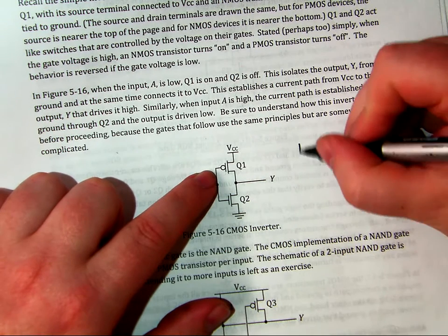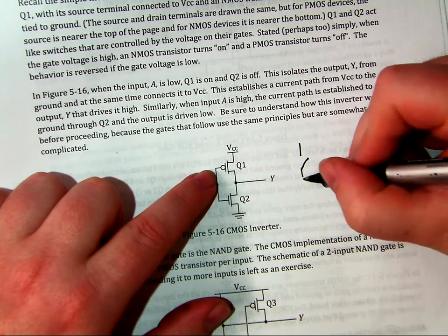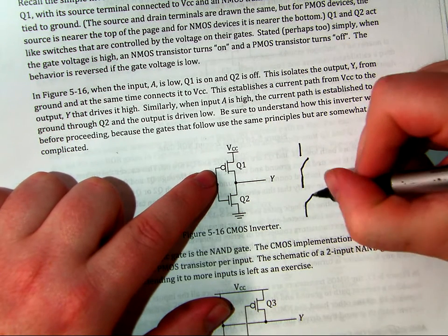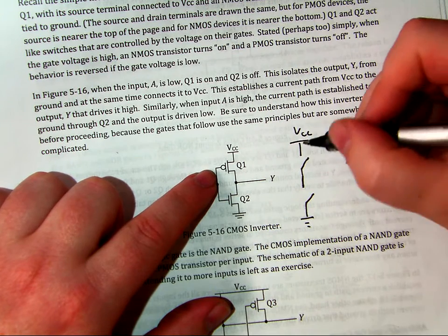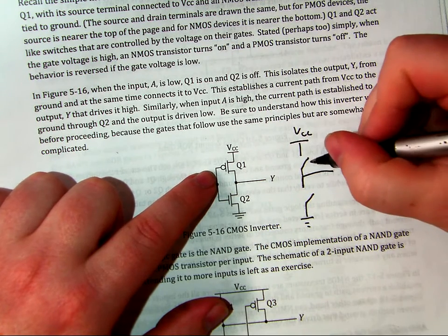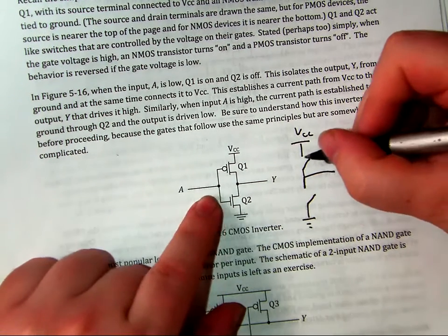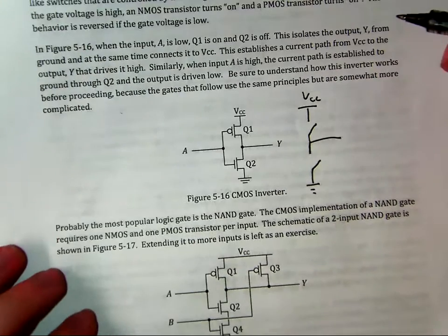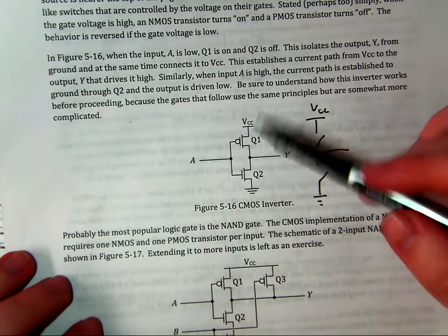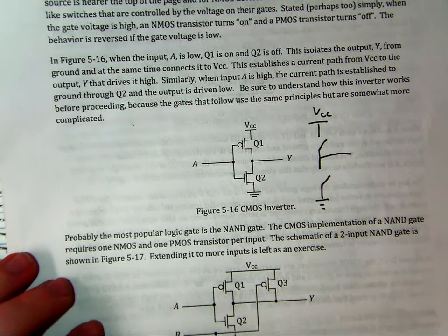So another way to think of this circuit is there's two gates, like so, with an output here, and only because of the shared input, only one or the other can be closed, so it's either high or low. Similar to that, it's not ideal, but that's the inverter.